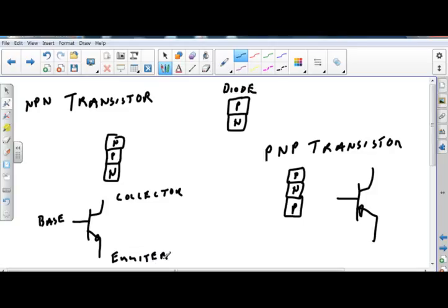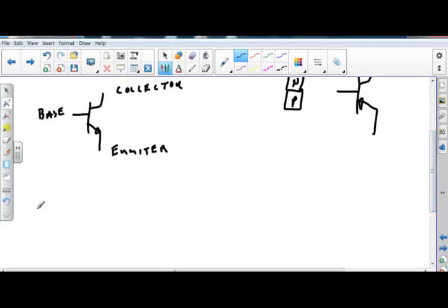But we call them that because that's what they were in our tube technology. So we took our vacuum tube technology. We now have this NPN transistor that's doing the same thing that the vacuum tube used to be doing, and we brought with us the same words associated with the vacuum tube. Now, the vacuum tube is something that is going to be electron flow, because we can't describe how a vacuum tube can possibly work if we have positive holes flowing.